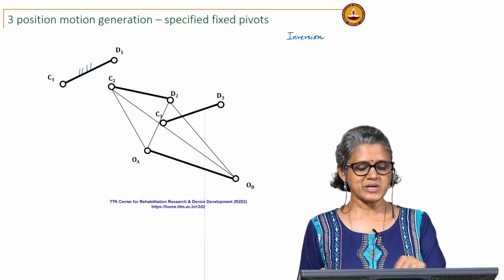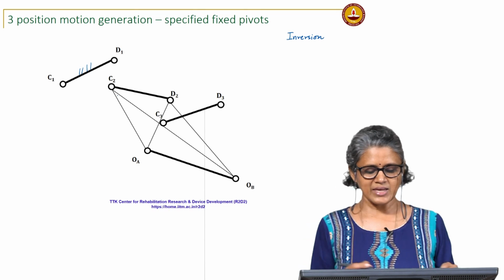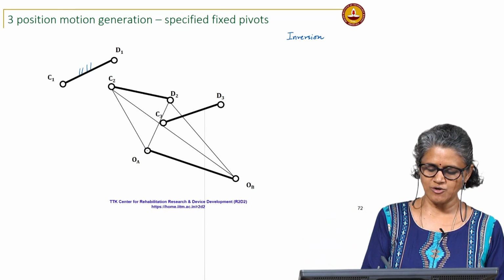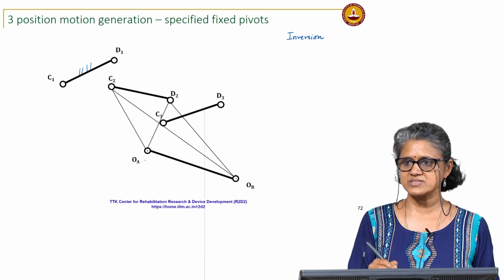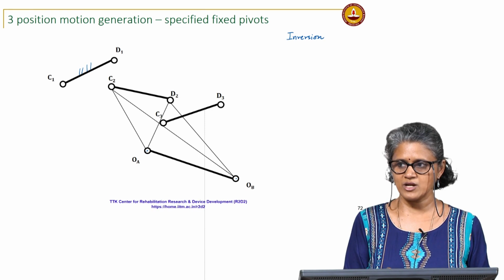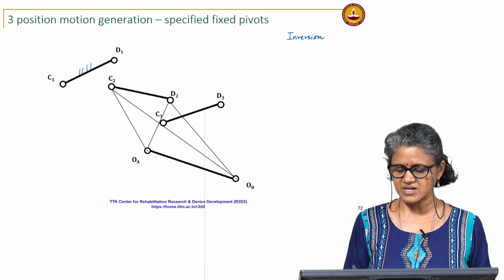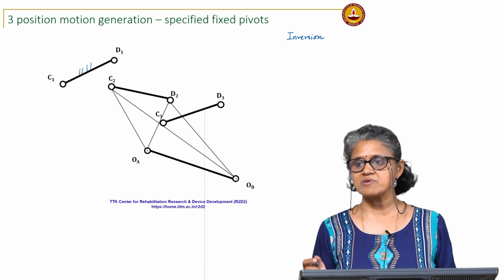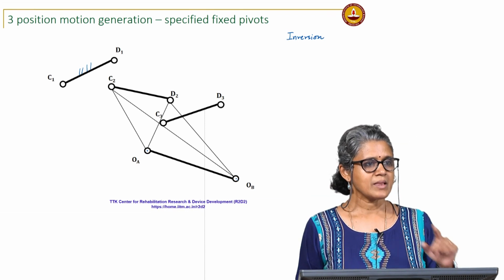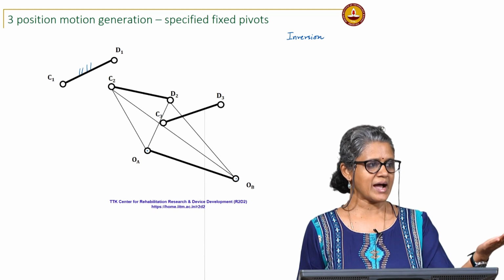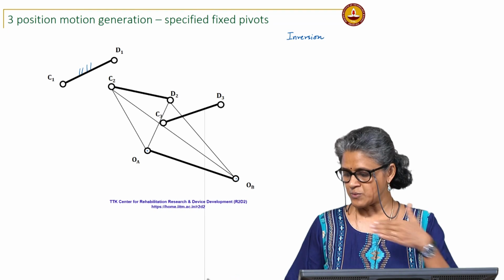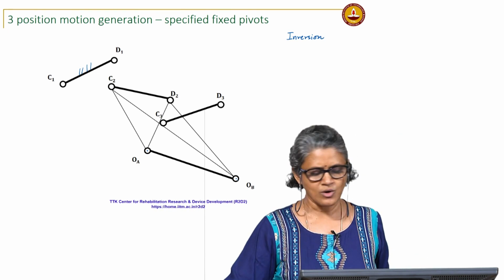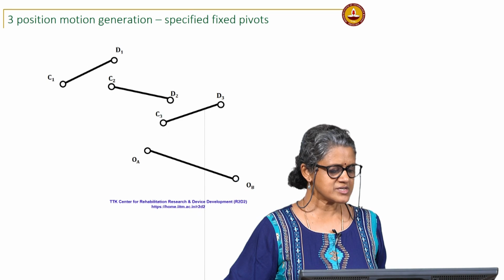With respect to C2 D2, I can find the location of OA and OB like this. I measure the distances, so I can locate OA like this with this triangle, and I can locate OB with this triangle. Now, I transfer that, because I am not moving, I am on C1 D1, onto that first position.